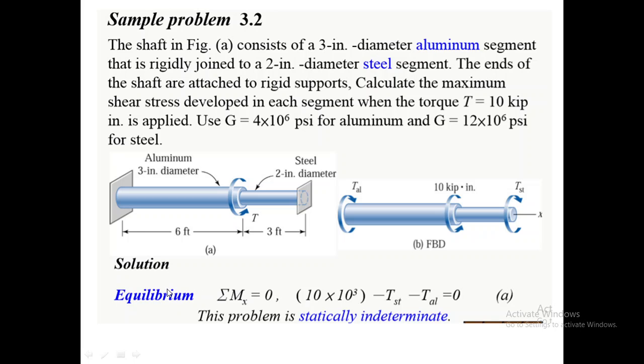So equilibrium equations alone are not enough to solve the problem. We may have to use some compatibility equations also for statically indeterminate problems. So in this session we look at stepped shafts where different torques are applied at different cross sections of the shafts, and we will try to design the shafts for this kind of application.